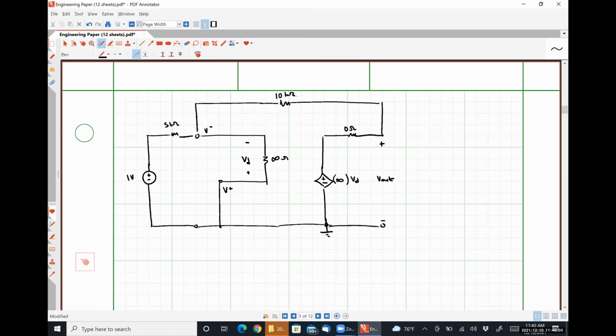Our voltage gain, we wanted it to be large so that the linear range was as small as possible. It didn't necessarily need to be infinite or anything like that. But we did want it to be large so that we are getting the most out of our nonlinear operation. And this guy being 0 actually probably didn't matter all that much because there was no feedback or anything like that in the comparator.